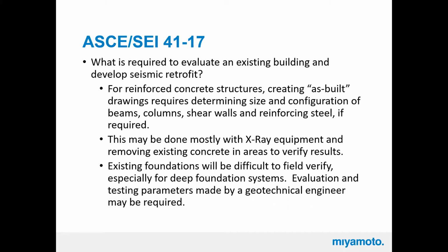As I said, for reinforced concrete structures, creating as-builts is quite the challenge. A lot of times we'll have to do some kind of investigation to determine what the actual rebar is, the spacing, the size, everything associated with the building. And a lot of times that's very difficult to do, or very expensive, X-ray and stuff. And there's a point about foundations. It's hard to dig up the whole foundation to see how big the footings really are, or if they're deep foundations, what they are and how deep they extend, because it's almost impossible.